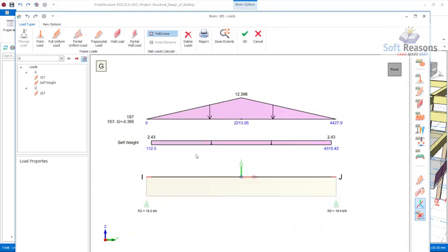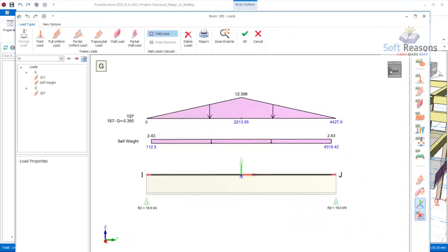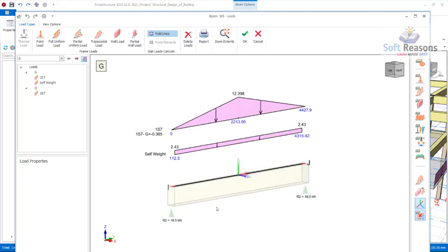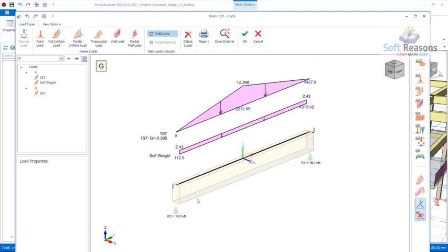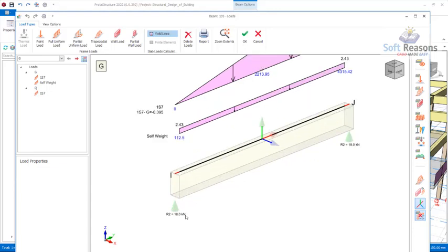You can click, hold, and then update this or use this to check the 3D of this beam. So originally you can see the self weight of this beam, and the load from the reinforced concrete slab. Okay, the load from the slab decomposes to the beams, and from the beams to the reinforced concrete columns. So this generates the reactions of 18 kilonewton on this beam.